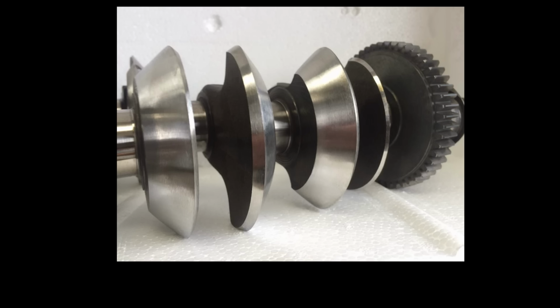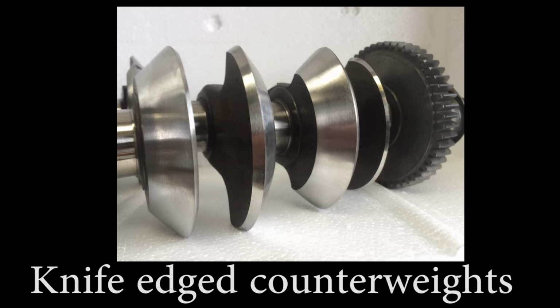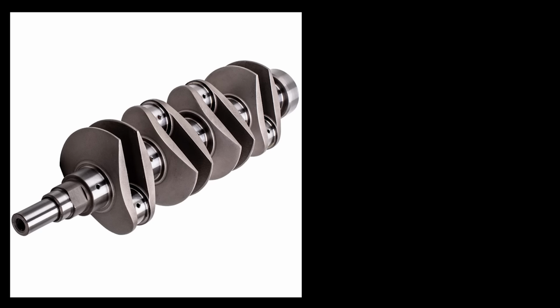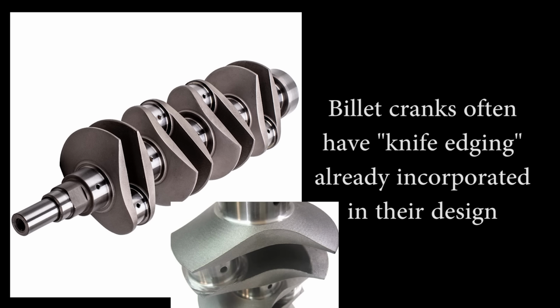And this is why you will sometimes see crankshafts intended for performance use being knife-edged. Knife edging means creating this sort of sharp, knife-like shape on the counterweights. The goal of the shape is, of course, to reduce the drag. On the other hand, billet crankshafts are often going to have these sort of aerodynamic shapes already incorporated in their counterweight design.